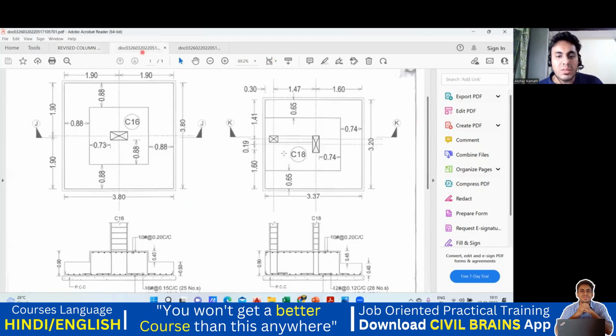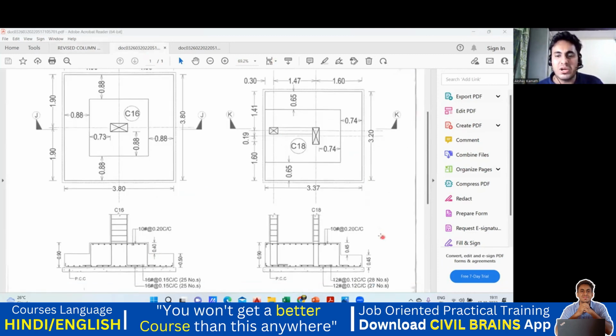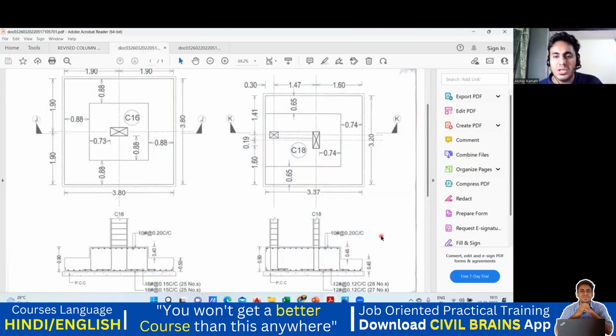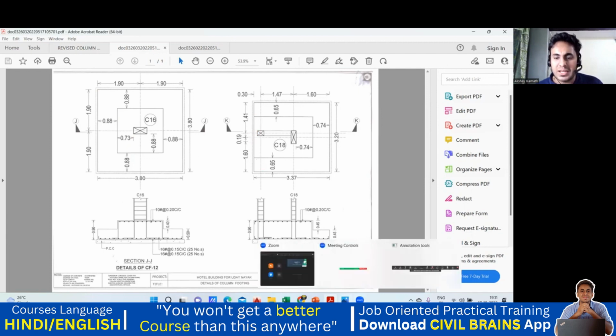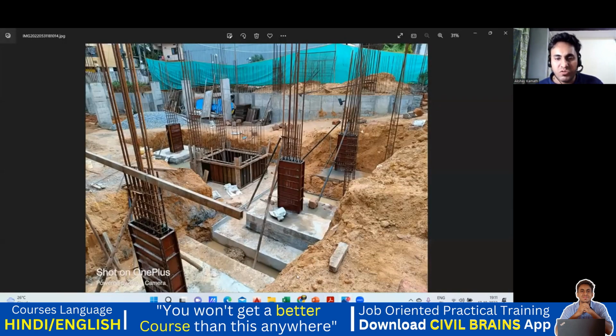Now in some cases you get this kind of footings again. So this is also a step footing, but here this was exactly at the center, right? Here it is almost at the corner side, like practically this particular image. You have a step footing, but here it is attached to the wall part. So what you are going to do, here also same calculation, nothing will change. Only your shuttering will change. Shuttering in the sense, this portion you will not do shuttering. I'll show you here.